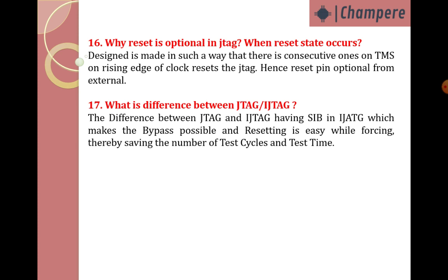Next question, why is reset optional in JTAG? When does the reset state occur? Reset is normally an optional pin. It is designed in such a way that consecutive ones on TMS, test mode select, on the rising edge of the clock reset the JTAG.